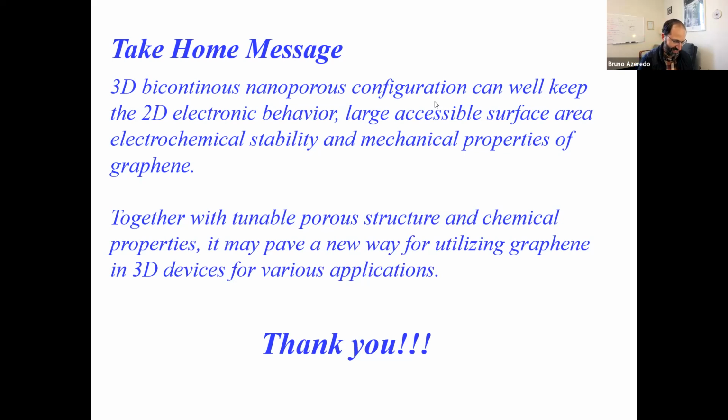But one of them I think is interesting: at the time you're doing CVD, that's a pretty high temperature, right? So you should have thermal coarsening of your metal scaffold happening maybe at the same time that you are precipitating the graphene. Is there a competition in kinetics of those two processes at the same time, or does one come first, then the other? What's the competition there? Is there one?